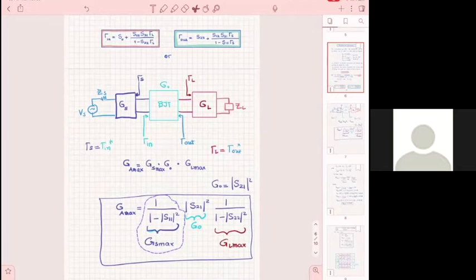All right, we don't know. It can be lower if the matching network is different. G sub S depends on how we design gamma S, how we select gamma S. So a different selection of gamma S, if we were not using this gamma S, but we choose a different gamma S, then GS will be different. For this gamma S, your GS is maximum.